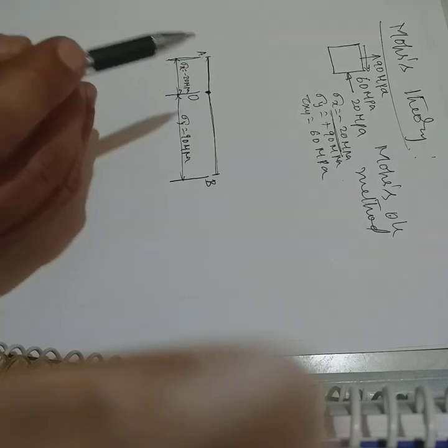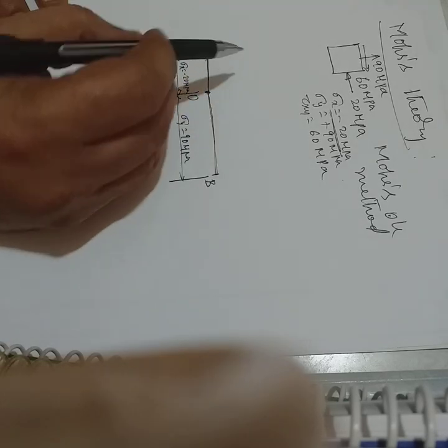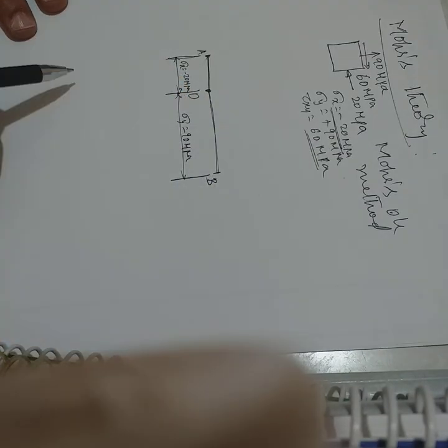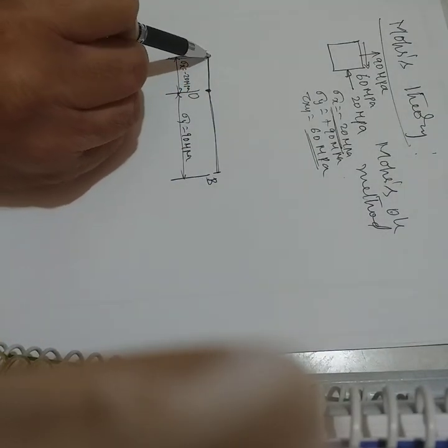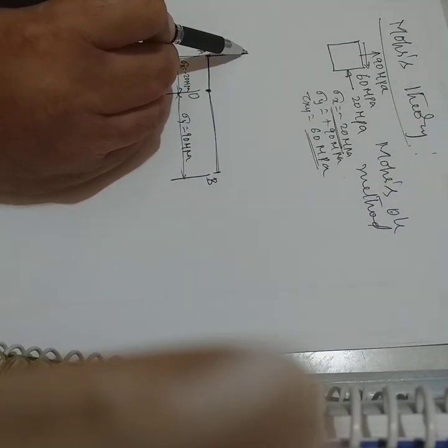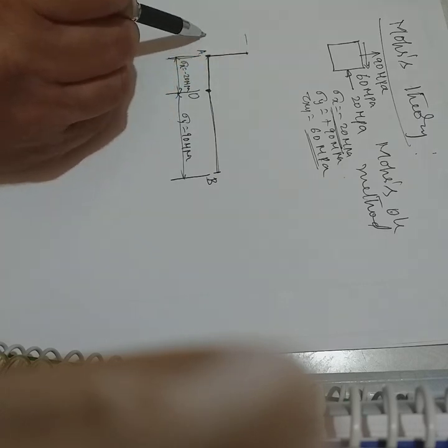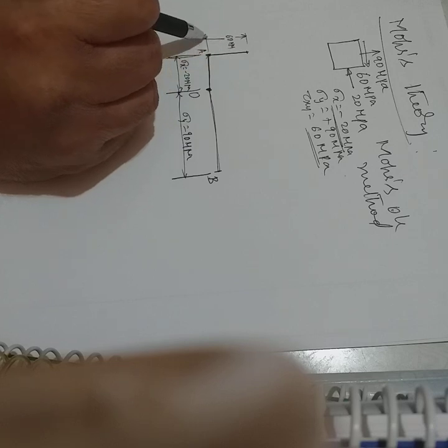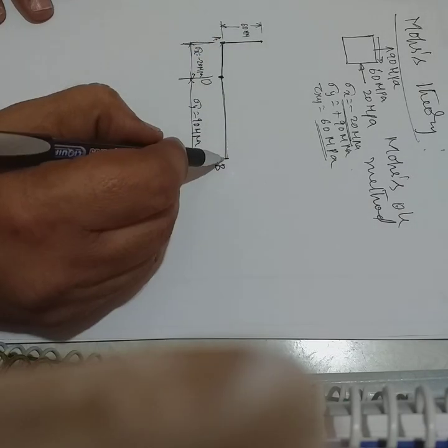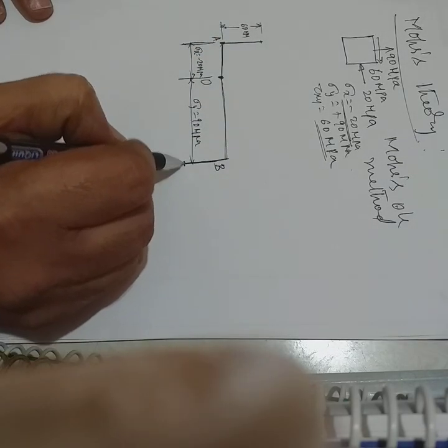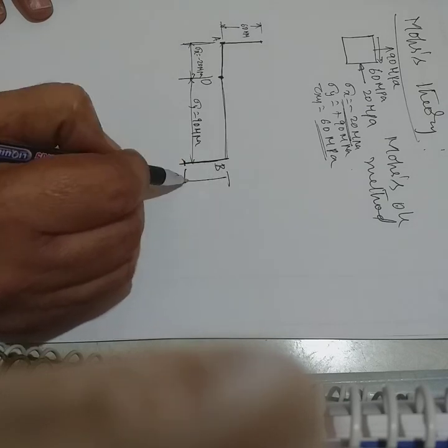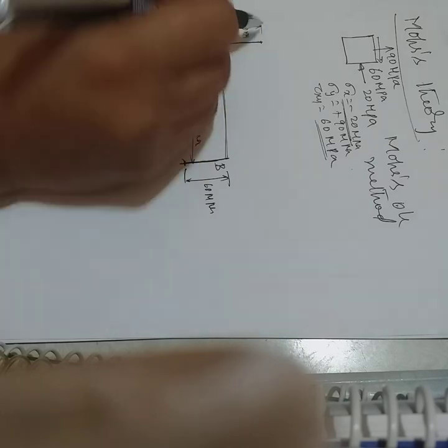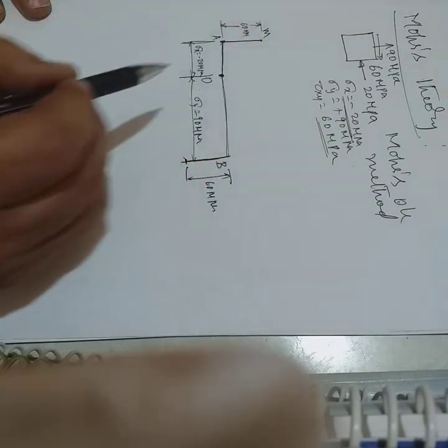Now what we need to do is, from point A, I have tau xy given by 60 megapascal. So from A you travel vertically up, to some suitable scale, as a representation of shear stress, to a height of 60 megapascal. From point B, travel to that scale again by 60 megapascal. I call it point M.